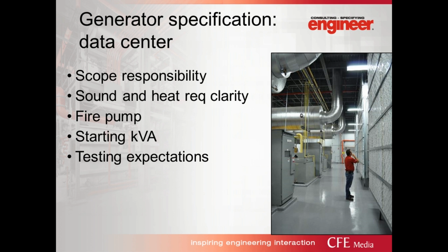Also, heat requirements. I think a lot of people don't understand the real cost implications of misinterpreting the heat rise on alternators as well. Those are real dollars. Those are decisions that may upsize the alternator needlessly, that would raise the cost of your vendor quotes or unfairly put someone at a disadvantage. Fire pumps, depending on your authority having jurisdiction, you need to be prepared to understand what are the kinds of breakers that are necessary to do that.